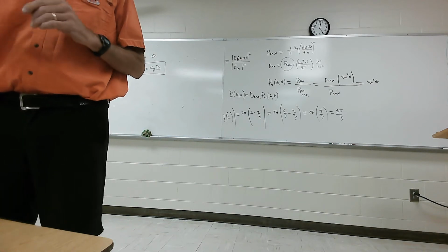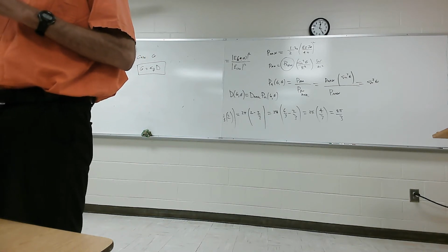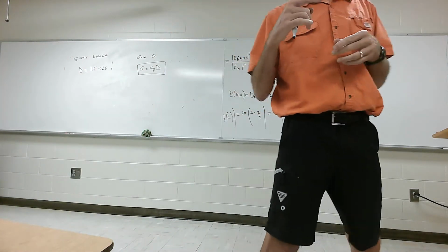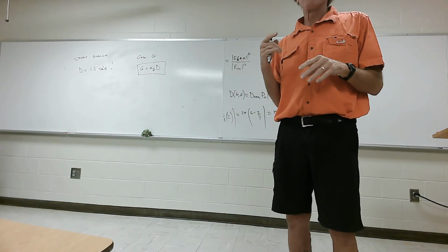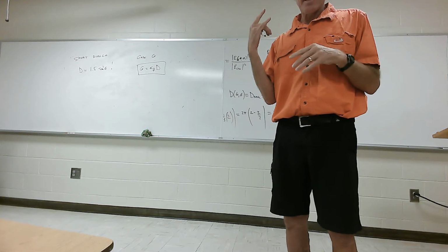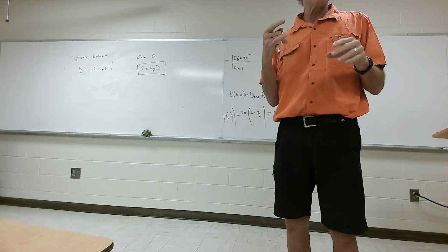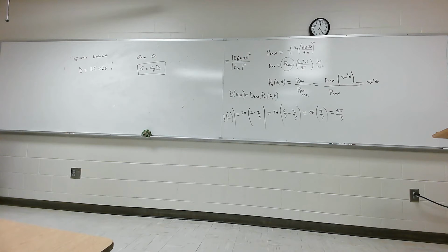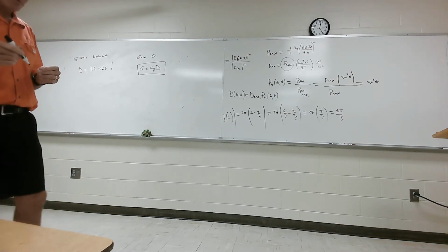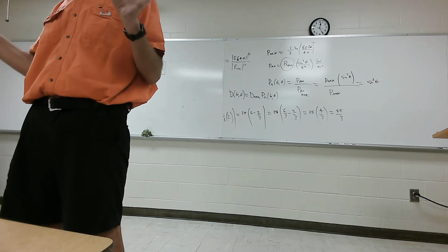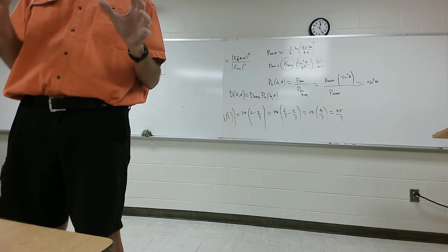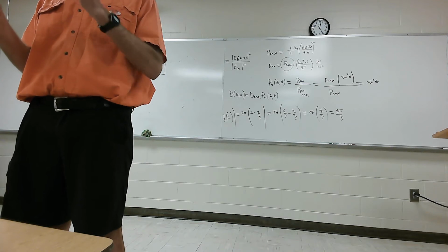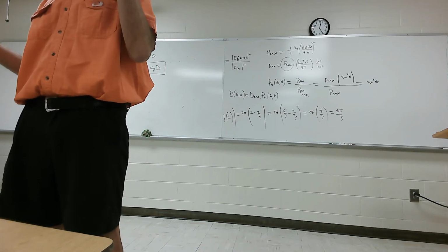And the guy called me and he said, listen, your antenna's got a standing wave ratio of 4, which means the efficiency is about 45%. Huh? Can't be. I remember the design. I went through everything, the impedance matching, everything. Well, this guy was an electrical engineer. He wasn't just a technician. So he went in and he says, I'm going to just open the top of this thing and see if something's amiss. And the guy who was doing the soldering, remember, a lot of technicians don't appreciate problems at high frequency. This is a 1.4 gigahertz antenna system. He left a huge solder ball. You know what solder balls are? You're not supposed to have it.